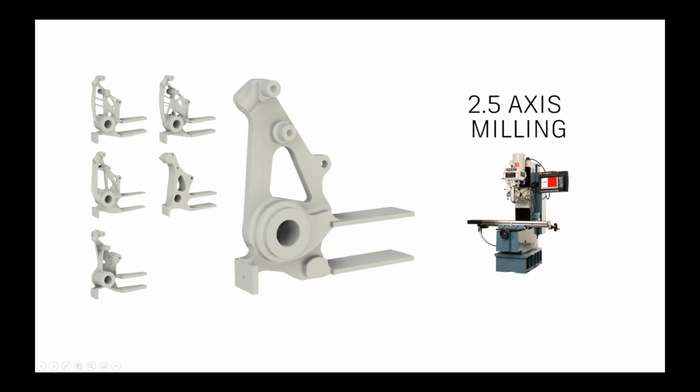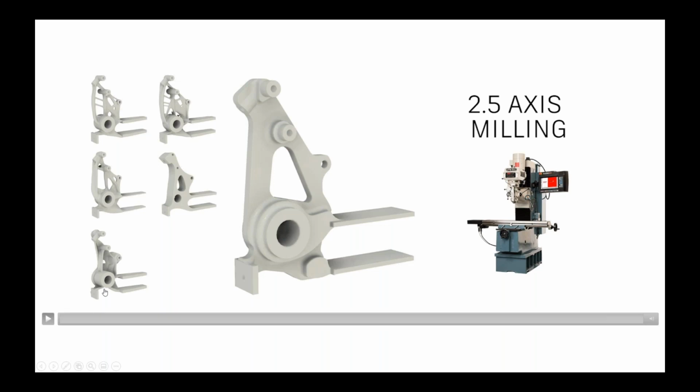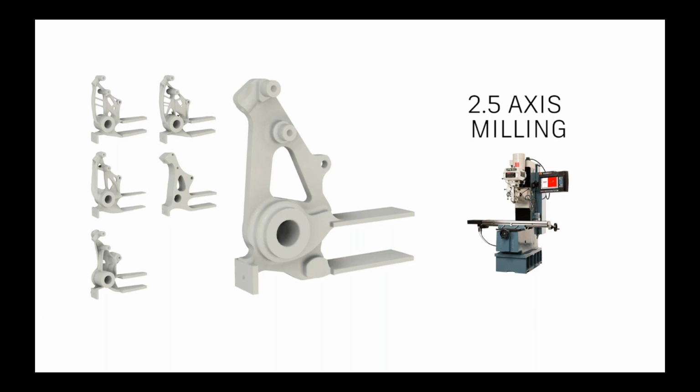The downside, or one drawback here: you used the specific example of wood. At this point in time, the program is looking for isotropic material properties, whereas wood is generally more studied as an orthotropic type of material. That said, one trick that we would utilize in the simulation world would be that when we enter the properties, we take the weakest direction properties, so that way we have a conservative design.